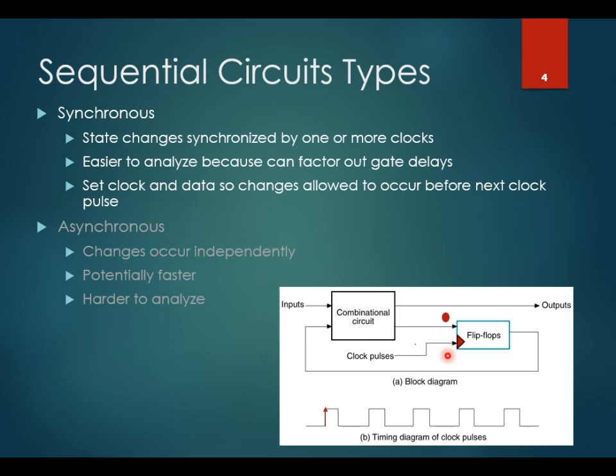This is to ensure the reliable data capture by the flip-flop or register when the clock triggers. So this is an important characteristic and timing analysis we need to perform if we choose synchronous sequential circuit method for the design.